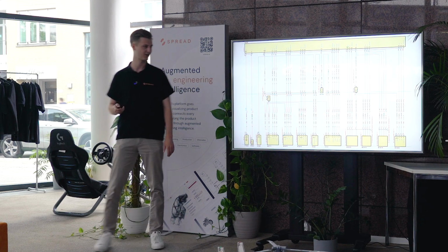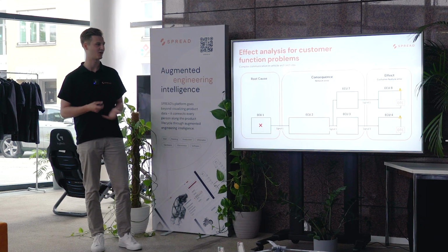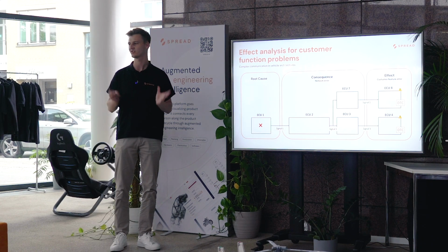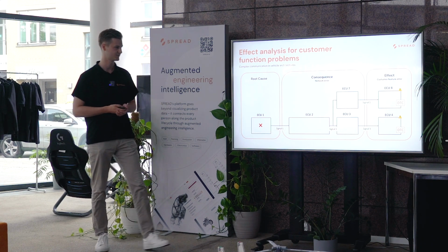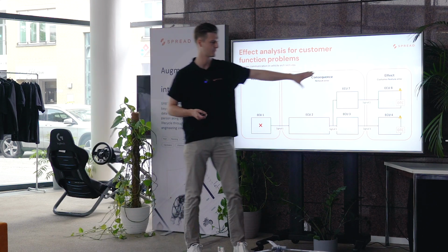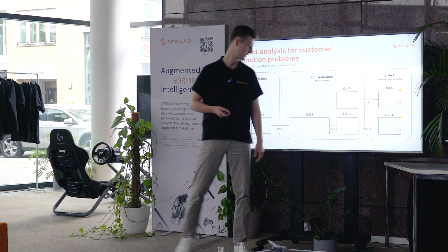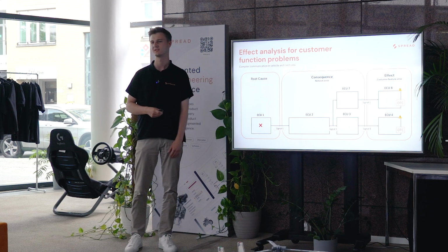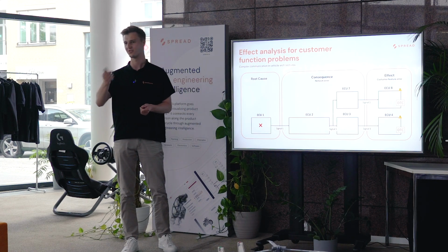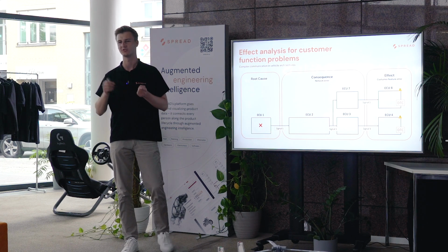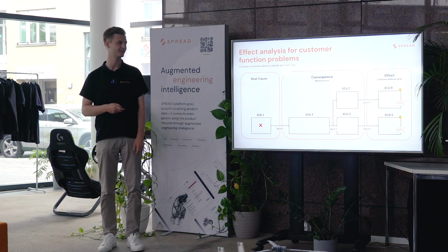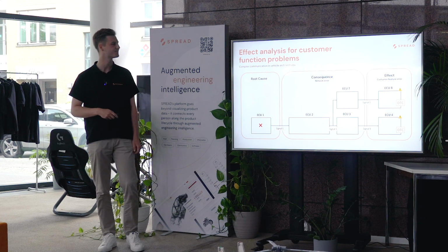So it's super complex. And this is exactly how one root cause for an error picture, we call it, could look like. So we have 2 DTCs thrown by 2 control units, but the actual root cause might be here. Maybe a wire is broken, some technician drilled through it, or a pin is broken, or a connector is not plugged in. These are typical use cases in the production sites.